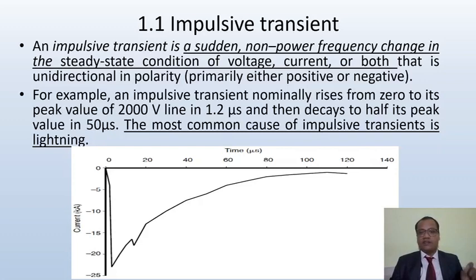That means when transients come into the voltage or a current, they go in any one direction, that is, positive direction or a negative direction. So here we can predict that when a transient is occurring in any one direction, and the sinusoidal supply changes its direction continuously, positive and negative, obviously the transient will occur within a very short period of time, within a half cycle, because only if it comes within the half cycle will it have a positive or negative polarity.